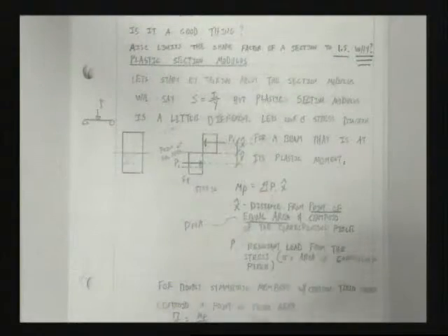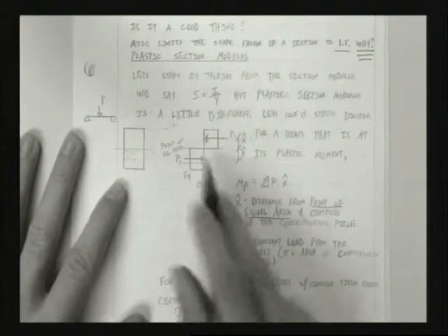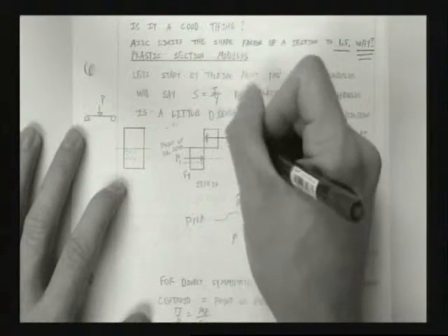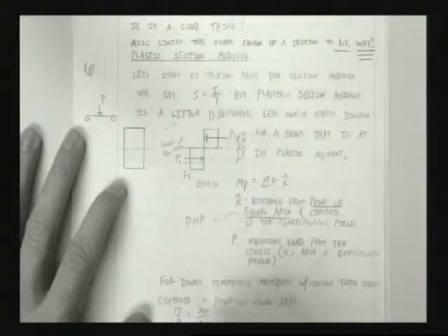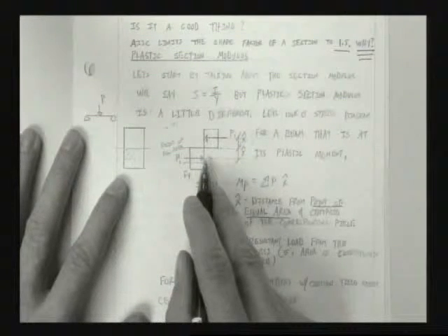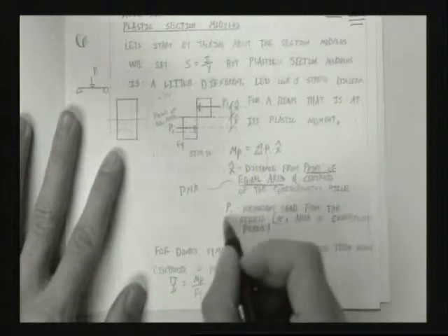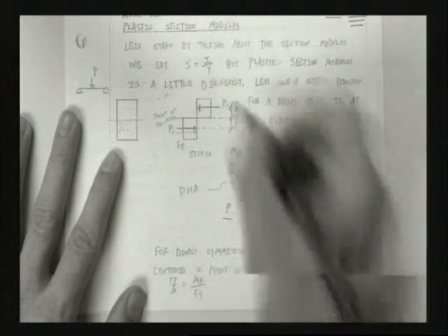But what you do is we'd find the point of equal area. We would plastify everything above that point, plastify everything below that point, find the resultants for each one of them, and sum it about the moment. It's pretty easy to do if it's a rectangle. There's the equation. That's all we're doing here. This resultant was P. X bar is the moment arm for each one, and we have to plastify it.